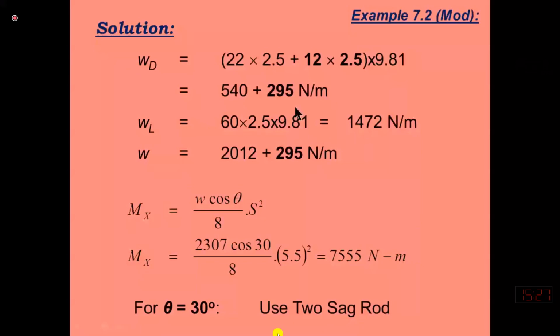And we are dealing with the self weight separately. Again, total load is this one, but we have shown the self weight separately and dead plus live load separately. This load will produce bending about the y-axis and torsion, and the self weight will only produce bending about the y-axis. And the total load will produce the moment about the x-axis, so Mx, moment about the x-axis.